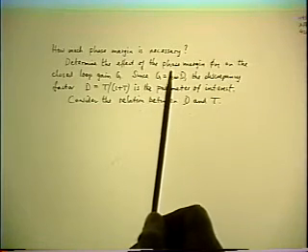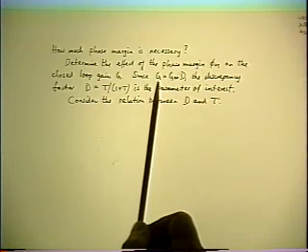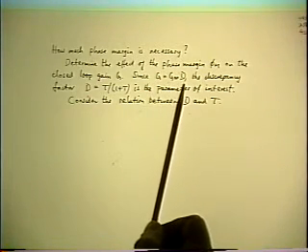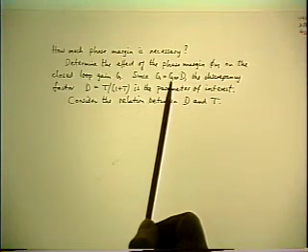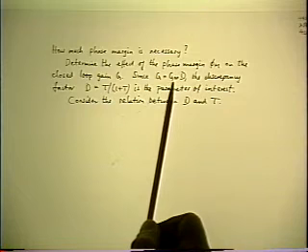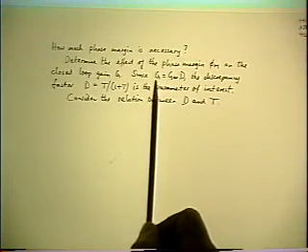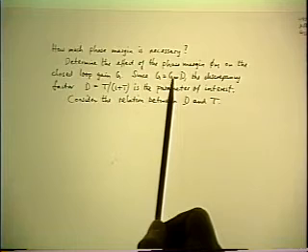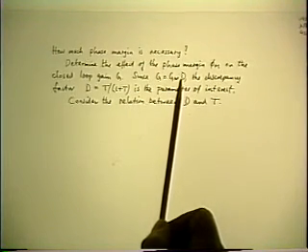So the most important property of the feedback system is its closed loop gain G, which is G infinity times D. Now G infinity is designed in right away according to the specification, and the feedback path is designed to do that. What's important is how close G is to G infinity. And that's what the discrepancy factor is about.